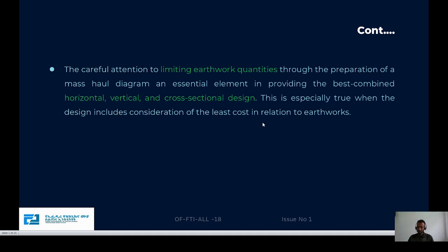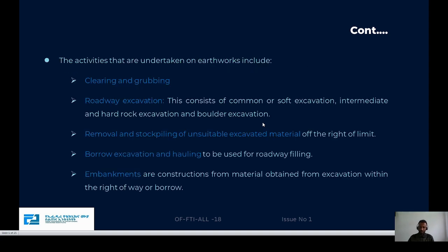For example, if a vertical curve is very steep, there will be a lot of cutting, and this cutting will increase the cost of the project. Also, if the vertical curve is very steep downward, there will be fill or selected material placed on the road bed, and this will generally increase the cost of the project.